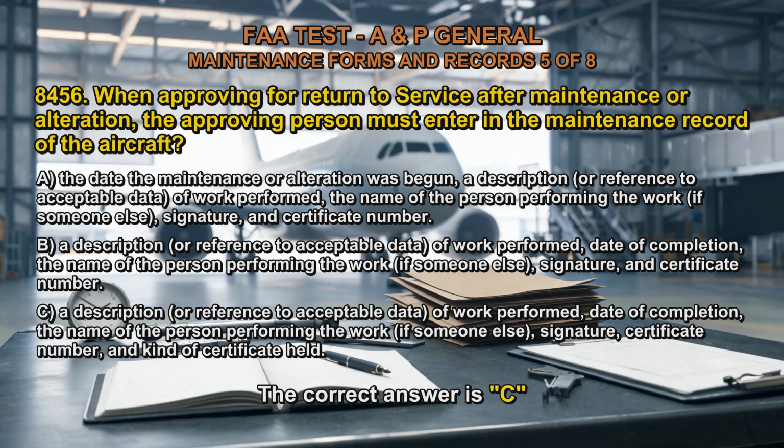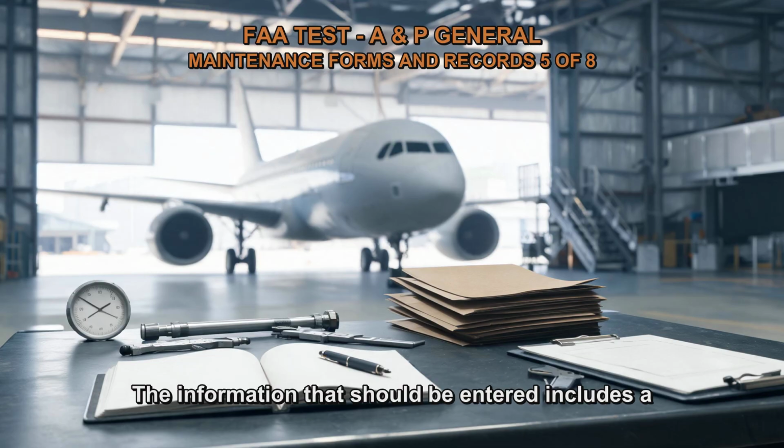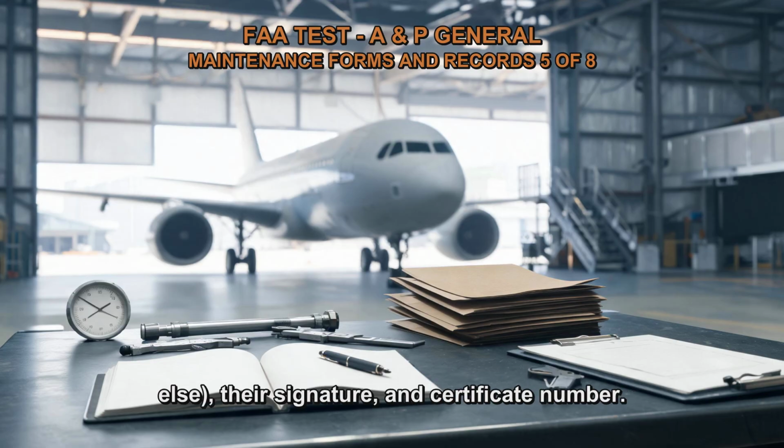The correct answer is C. The information that should be entered includes a description or reference to acceptable data of the work performed, the date of completion, the name of the person performing the work, if someone else, their signature, and certificate number.